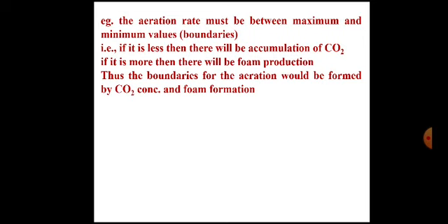So these will be the two boundaries for aeration, CO2 concentration and foam production. So the aeration rate should be maintained so that there should not be accumulation of CO2 and there should not be formation of foam as well.